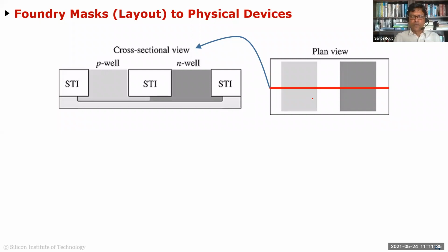Okay. So here I'm showing that you just have one inverter, and you had a P well and an N well, and basically it's a well with a certain doping, and you drew a mask, right? So this is what you drew in the layout. And sometimes you don't even realize you drew this, because you use what's called a P cell. You just use an abstract, you place it in, which has tens of layers inside it. But the foundry will segment out only the layers for each particular processing step.